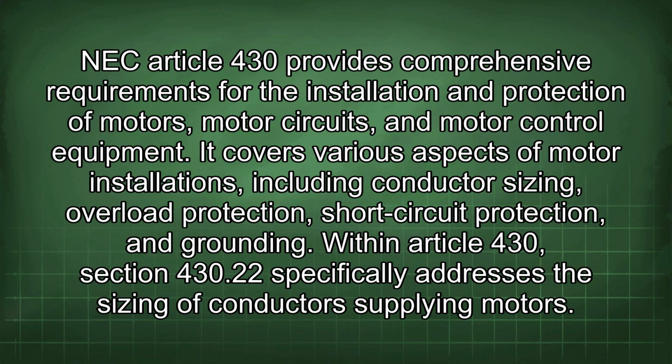NEC Article 430 provides comprehensive requirements for the installation and protection of motors, motor circuits, and motor control equipment. It covers various aspects of motor installations, including conductor sizing, overload protection, short-circuit protection, and grounding. Within Article 430, Section 430.22 specifically addresses the sizing of conductors supplying motors.